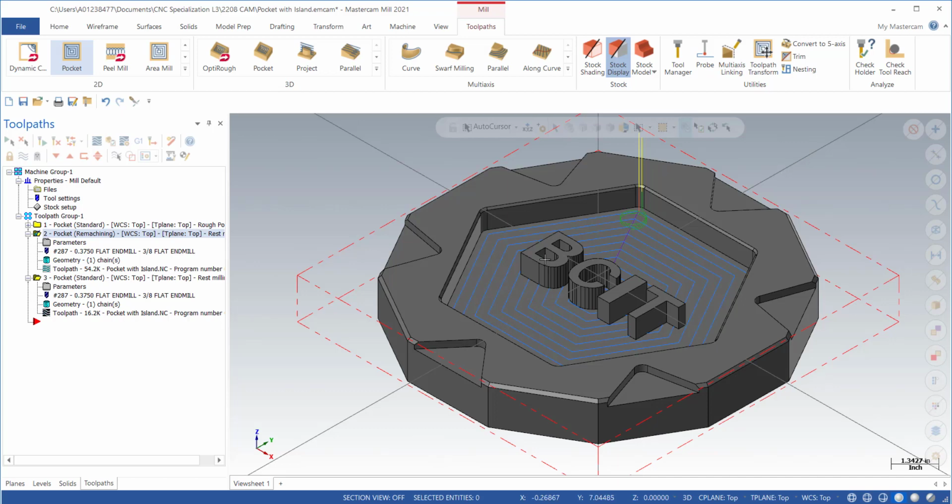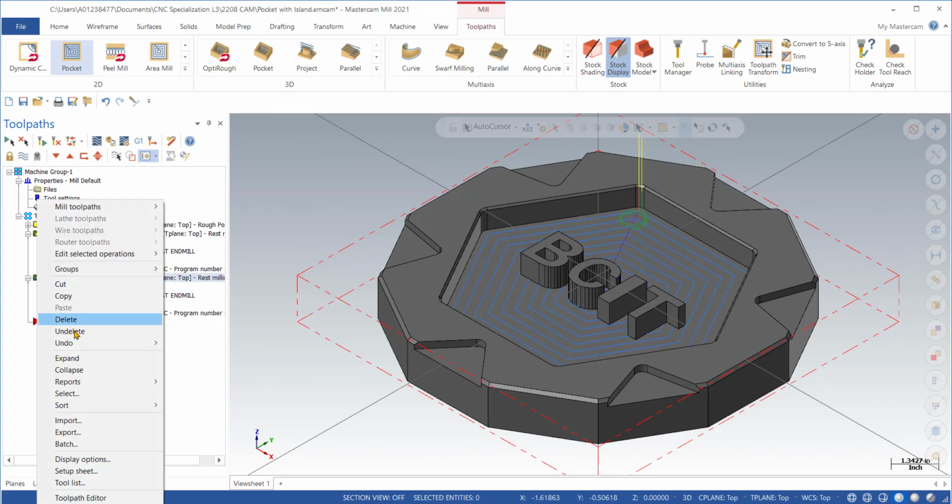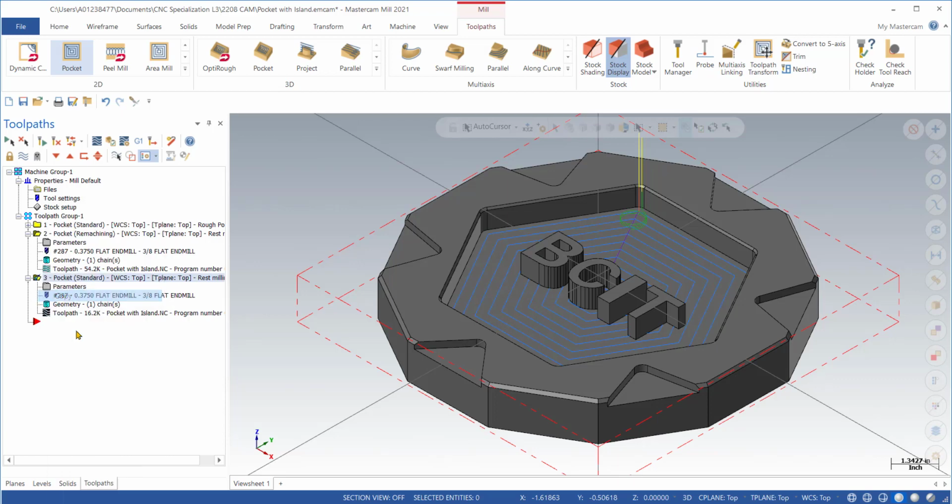So one more time, the same toolpath here. I would just copy paste the same toolpath. And this time we would turn off the roughing and only leave the finishing pass, and also turn on the cutter compensation. Okay, so the copy, paste.